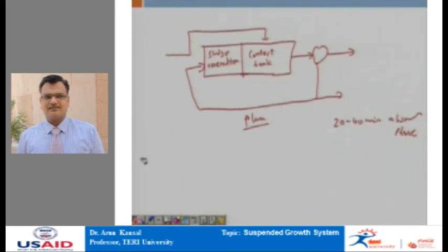So, what we have seen is that absorption takes about 20 to 40 minutes, and then a significant amount of time is required for assimilation and dissimilation. In the activated sludge process, which we have discussed earlier, these two processes occur in the same tank, but in the contact stabilization process, the two phases are separated and occur in different tanks. That is, we have mainly the absorption here and the assimilation and dissimilation process happening in this tank.